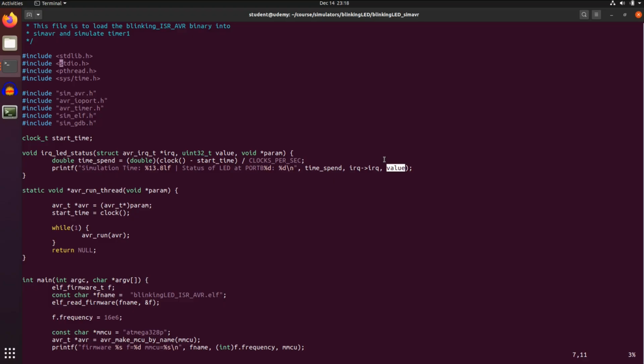For instance, I could attach an Arduino to the USB port, which then takes care of its onboard LED if the IRQ hook is called and the data is transmitted through USB from the PC to this Arduino. For now, I just print the kind of IRQ that happened and the current value of the pin.